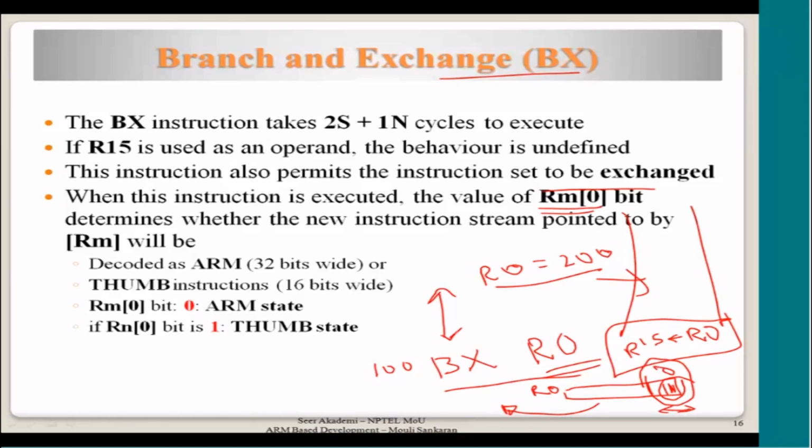Moving back or moving to, it doesn't matter, from ARM mode to thumb mode. That means going forward, whatever instructions you encounter from the memory, please read them as 16-bit wide instructions. Internally process them as 16-bit. You run it in thumb mode. It's a different mode of a processor, but it has to be communicated to the processor that it is going to be 16-bit wide instructions.